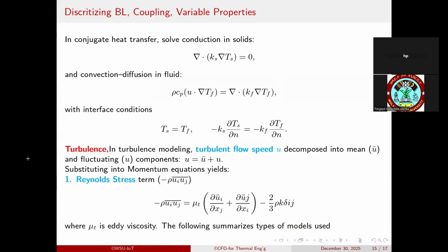All the previous topics are with the exception of the general basic segregation, with specialized techniques. The flow speed U is decomposed into U bar, the mean, and a fluctuating part, U prime. Turbulence is categorized within certain set of limits, and the fluctuating part is averaged, known as the Reynolds-averaged Navier-Stokes model.